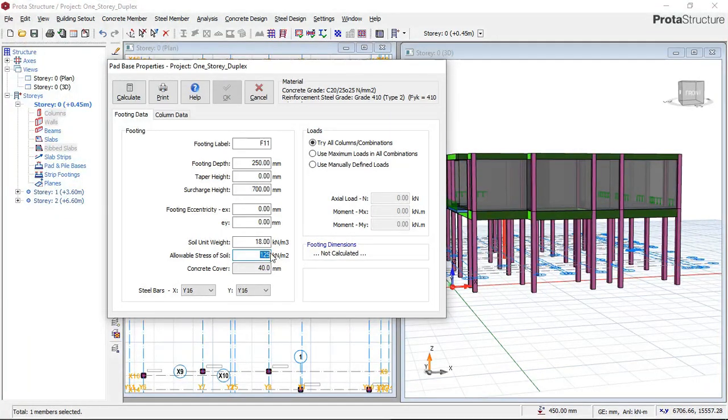Then once you have done this, the next thing to do is to go to this place called T-bars. You have to select the size of the reinforcement for your footing. Now, I will advise you, because you also have to make your choice on this area. If you're designing for a one-story building, I will advise that you use diameter 12 as your size of reinforcement. But once you're designing for a two-story building, I always advise you use diameter 16 because of the weight of the building. Because this is just a one-story building with just one slab, and the soil bearing capacity is not that bad, I'll use diameter 12.